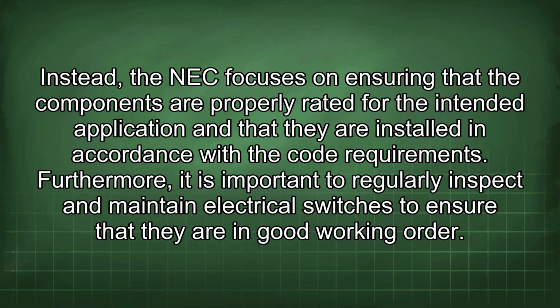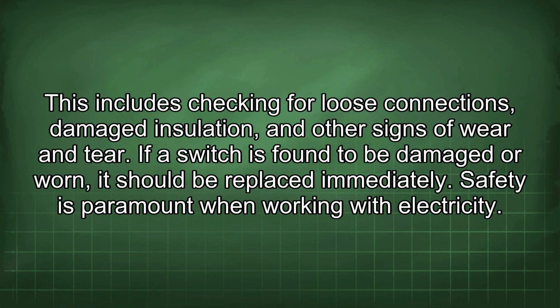Furthermore, it is important to regularly inspect and maintain electrical switches to ensure that they are in good working order. This includes checking for loose connections, damaged insulation, and other signs of wear and tear. If a switch is found to be damaged or worn, it should be replaced immediately.